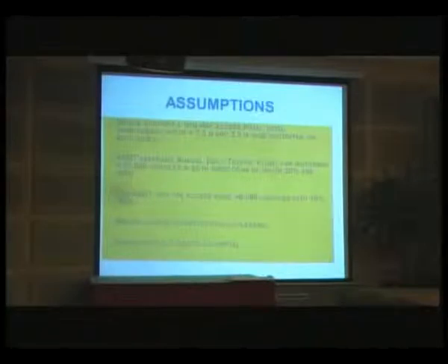So that's an annual traffic flow rate, of which 20% are heavy goods vehicles. And as far as the access road is concerned, so that's the road on the bridge, we assumed that it carries 6,000 vehicles, of which 10% are heavy goods vehicles. The bridge is located in an area of outstanding natural beauty, and it's going to be in a fairly prominent position, and so we wanted an aesthetically pleasing solution.